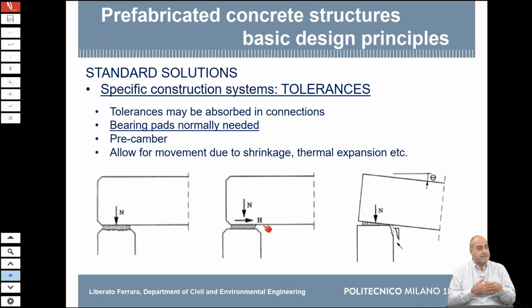So, for example, never put a dry contact, concrete to concrete, because this first of all brings very high friction. And there have been cases in the past where this very high friction is a force applied at the interface between the beam and the column, not at the axis of the beam. So this force has a bending moment with respect to the axis of the beam. It's a negative bending moment for which you may not have designed your beam.